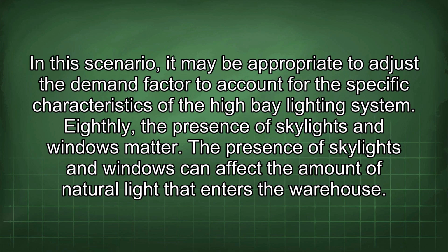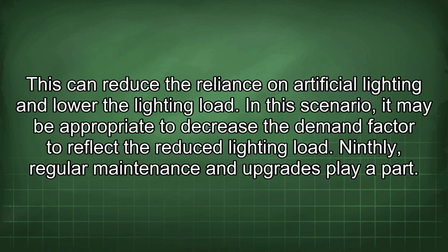Eighthly, the presence of skylights and windows matters. The presence of skylights and windows can affect the amount of natural light that enters the warehouse. This can reduce the reliance on artificial lighting and lower the lighting load. In this scenario, it may be appropriate to decrease the demand factor to reflect the reduced lighting load.